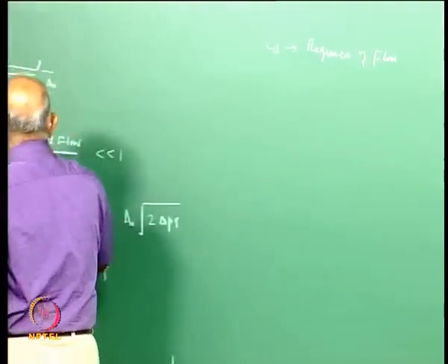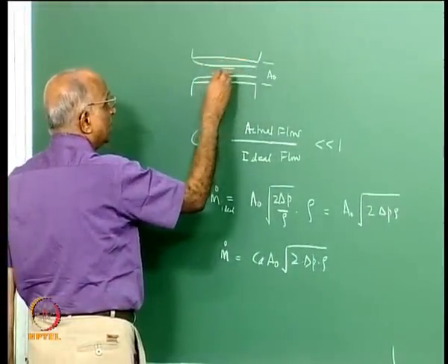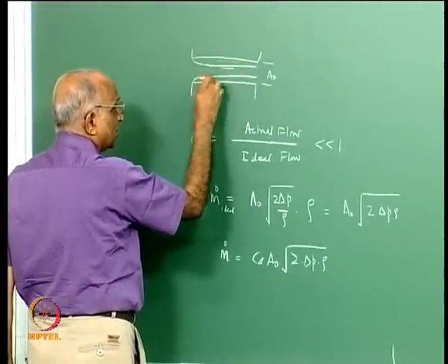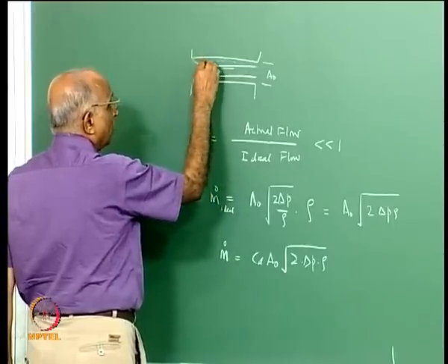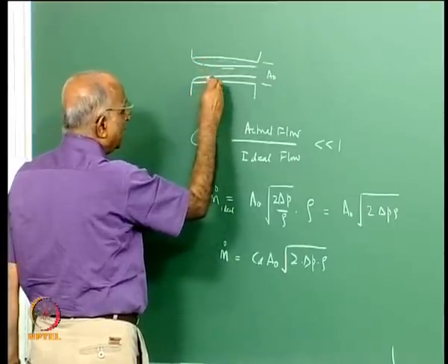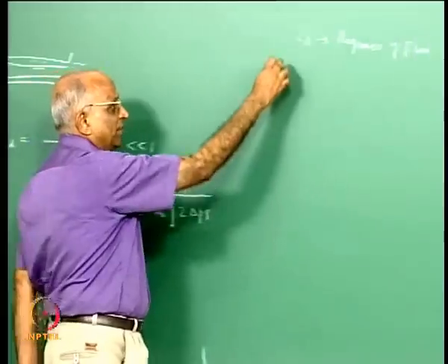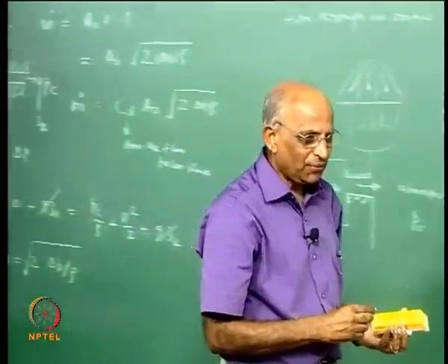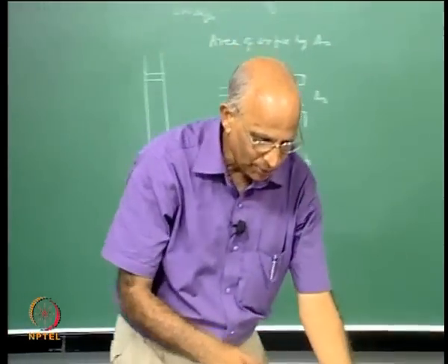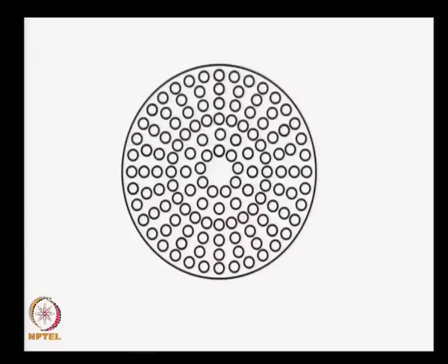The flow sometimes runs full, such as it happens when the orifice is large, sometimes with cavitation it gets separated, or when the orifice is very small, due to the Vena contracta it gets separated, and therefore for the different conditions we would like to examine the value of CD, which I do subsequently. I thought we should not spend too much time on it, because we are shifting the topic from liquid propellant rockets to one particular element of it.